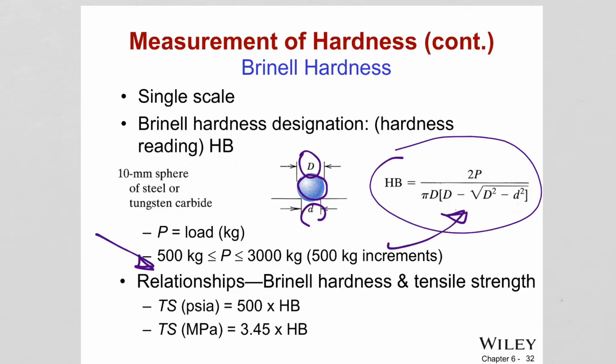There has also been found a relationship between the tensile strength and the calculated Brinell hardness values, and these equations are given here depending on which units you want to use. If you use PSI or megapascals, you just multiply the Brinell hardness by a certain number and calculate the tensile strength. So this relationship is important.